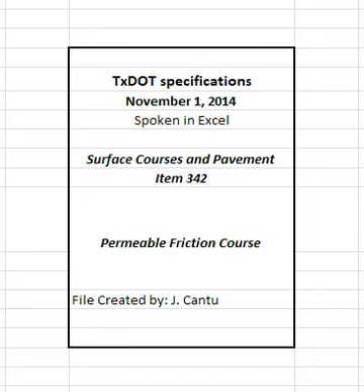Comply with all regulatory requirements stipulated for RAS by the TCEQ. RAS may be used separately or in conjunction with wrap. Process the RAS by ambient grinding or granulating such that 100% of the particles pass the 3/8 inch sieve when tested in accordance with Tex-200-F, Part I. Perform a sieve analysis on processed RAS material before extraction, or ignition, of the asphalt binder.